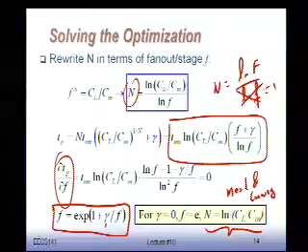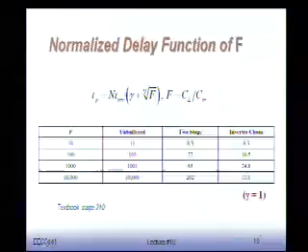This is a very important result because it actually not only is going to work for inversions, but later on we'll basically expand it also if I would have, let's say, complex gates like NAND gates, NOR gates, XOR gates, and/or invert gates, all those type of things. Because you have these very complex logic functionality blocks. How should I size the gates? Such a way that I get minimum delay. We're going to fall back to similar type of mechanisms to analyze that.